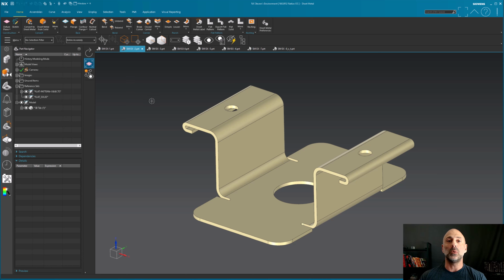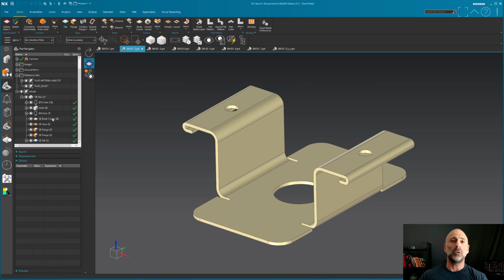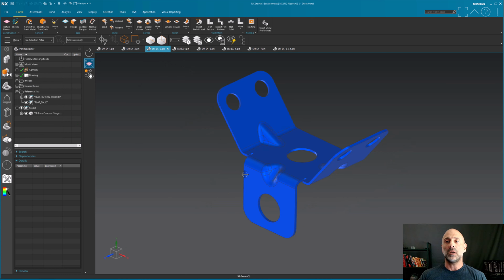When we get into here and here, you'll note that you have a flat pattern, or if you have objects and curves, and how to make the flat patterns, and basically going between your sheet metal application and then going into the modeling application, because there are some things in modeling that you need to do in order to finish off parts. So we swap between that, and then we get into gussets and easy ways to apply those, and then of course setting up datums and referencing datums.